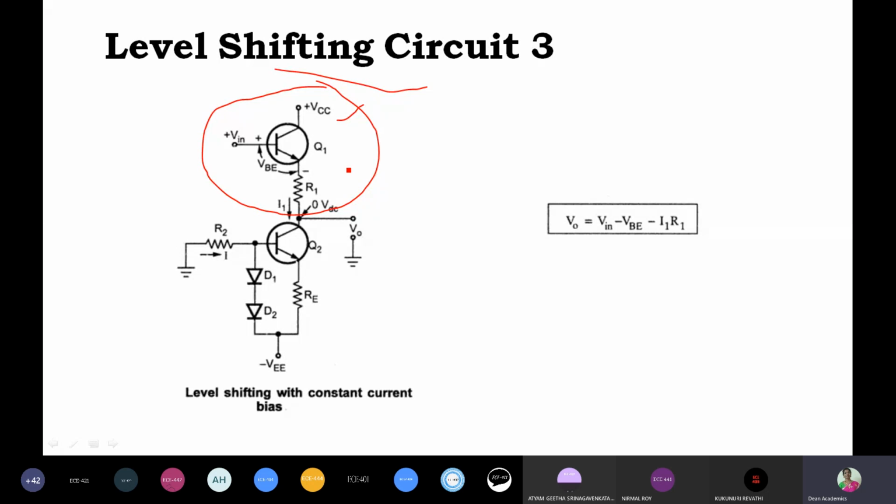So we have added one more resistor R2. With R2 we will be able to control the output voltage to the maximum possible extent, but it is introducing two more problems. That is, it is affecting the gain and output resistance of the amplifier. So therefore we go for another circuit arrangement.